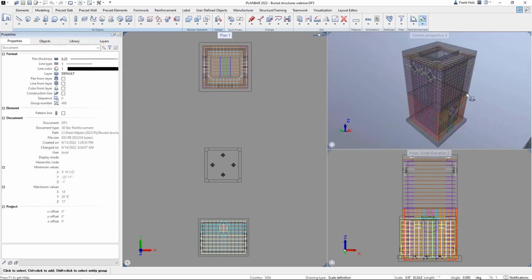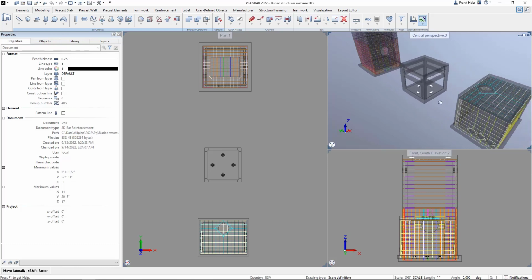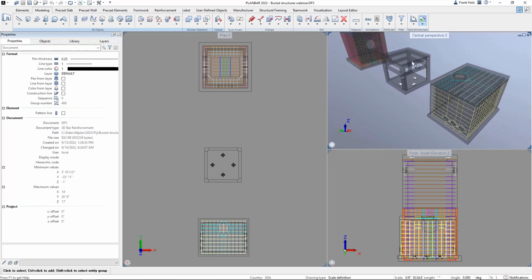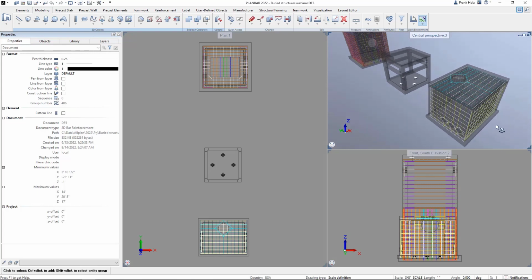So like I said, just showing off a few of the different vaults that I've been privy to from our customers over the years. They're all different shapes and sizes. They incorporate different fixtures, as we call them, these inserts, whether they're lifting inserts or terminators or boots, what have you. So any kind of shape you can really imagine. You can model it and reinforce it in Allplan, and with our basic shapes, you can model and reinforce it almost instantly after you enter the parameters.